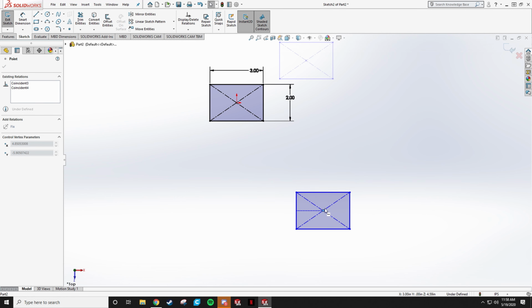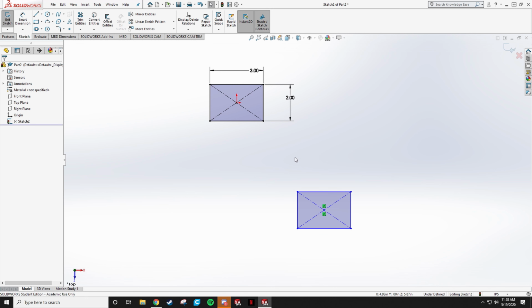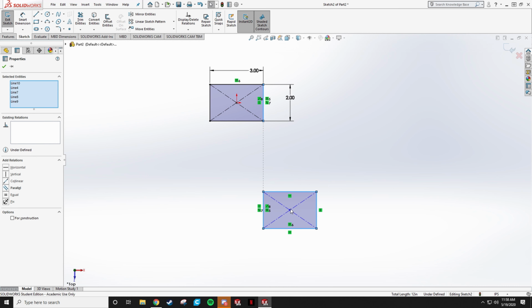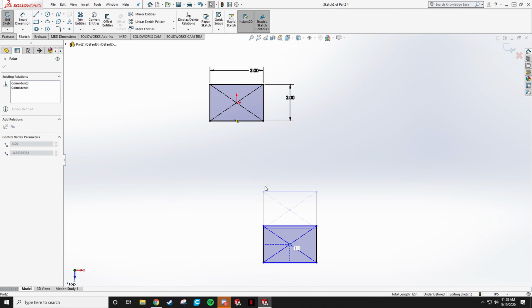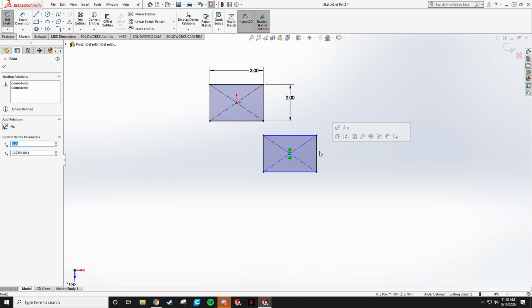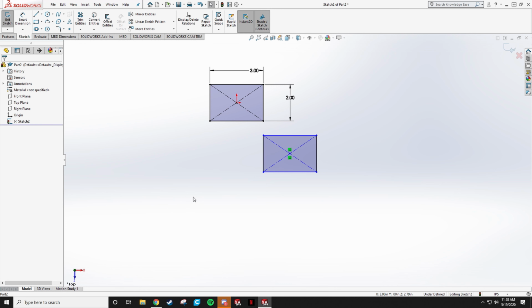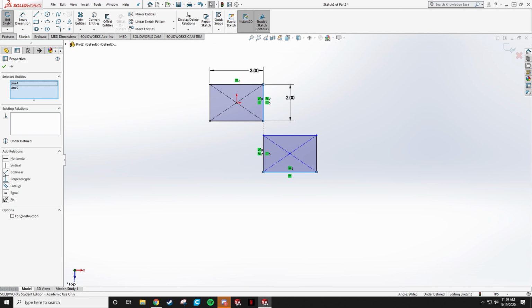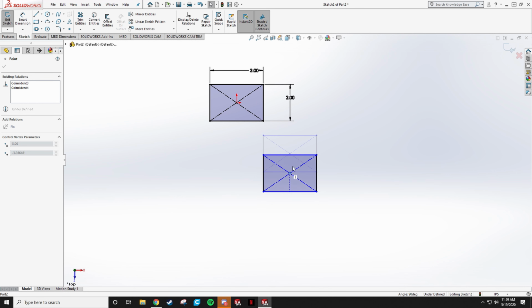Before, I can drag it anywhere, but as soon as I do this and say collinear, can't drag it sideways. I can drag it up and down because it'll still be collinear and all that fun stuff. So you can mess around with these. You can fix triangles, so even if they don't have a dimension or anything, they'll stay the same. Tons of other ones, so you can look at the conditionings, and they'll pop up which ones you can use and which ones you can't use, so that's very helpful, it prevents you from making mistakes before they happen. So yeah, those are some conditionings.